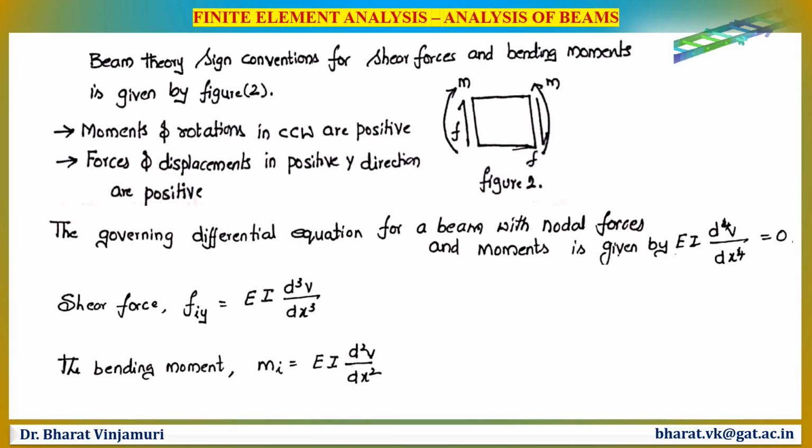The sign conventions according to this theory are represented in this figure. Now, the shear forces which are in positive y direction are considered as positive, and the moments and rotations which are in counterclockwise direction are considered as positive.